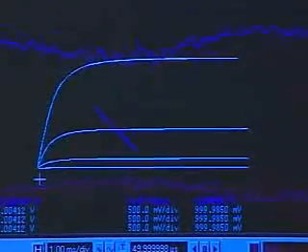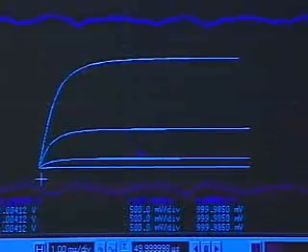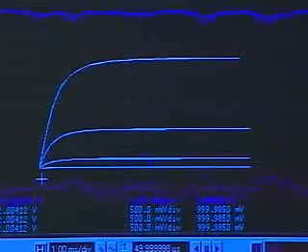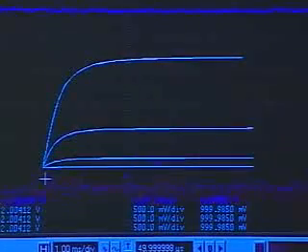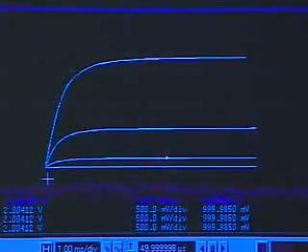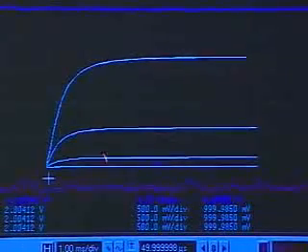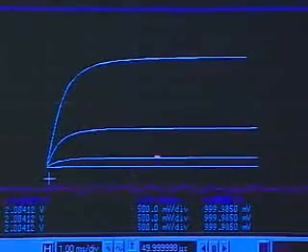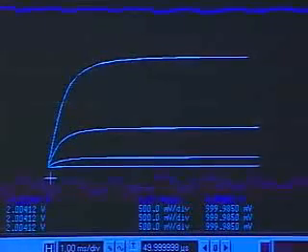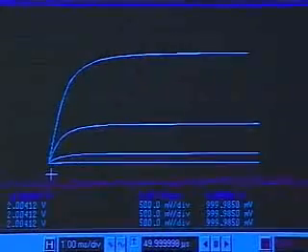Okay, now you should hear the volume go down and distortion. So notice now that the bias is way down here, so the gain is very low, and plus there is distortion because of cutoff. Now what I'll do is blast it up here, and you'll see that the volume has gone up, but then you see distortion again. And let's see if we can stand the volume here.